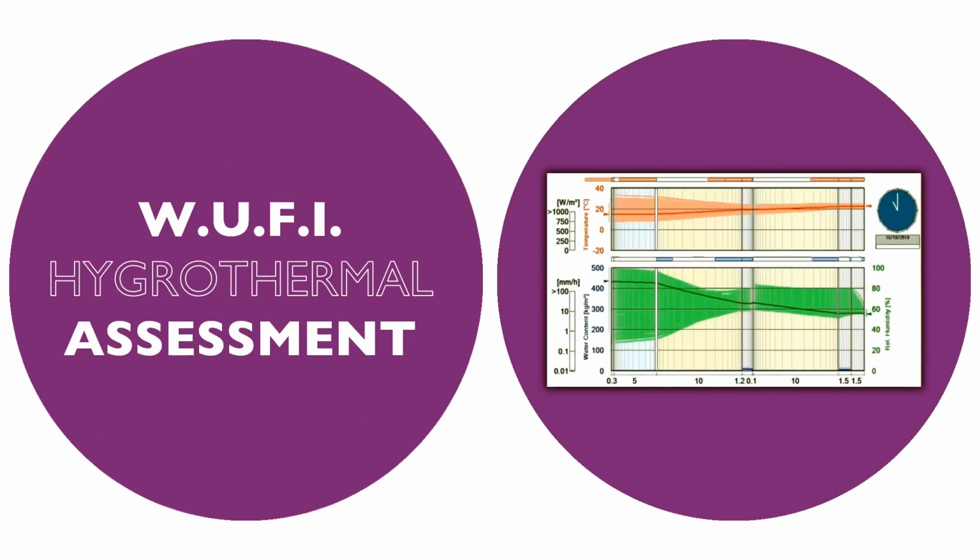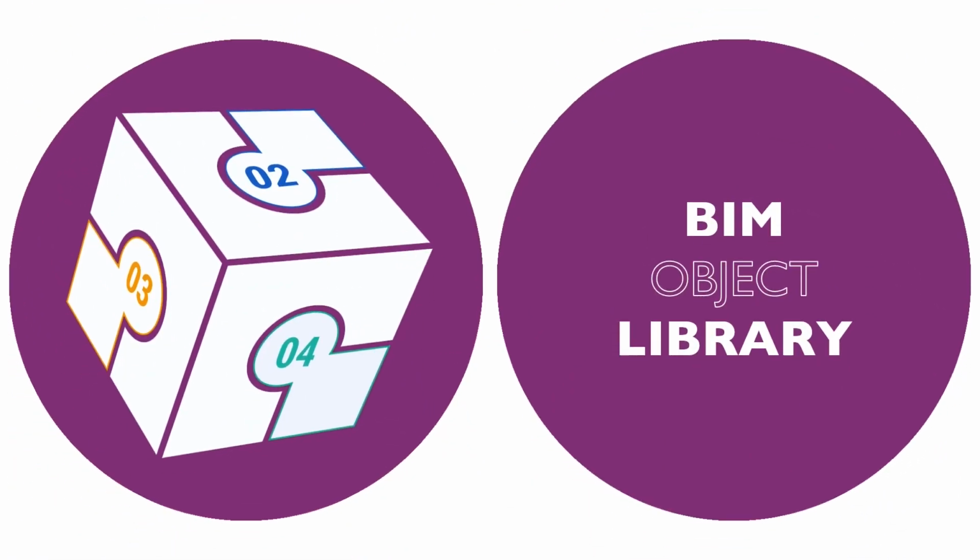Alongside this, we can also undertake WUFI assessments to ensure the specified construction is able to deal with the moisture loads placed on it, and to optimise the material specification to ensure the most efficient envelope is achieved. We also provide a full library of BIM data and template constructions for all our products, available in both Revit and IFC formats for compatibility with a wide range of software and systems.